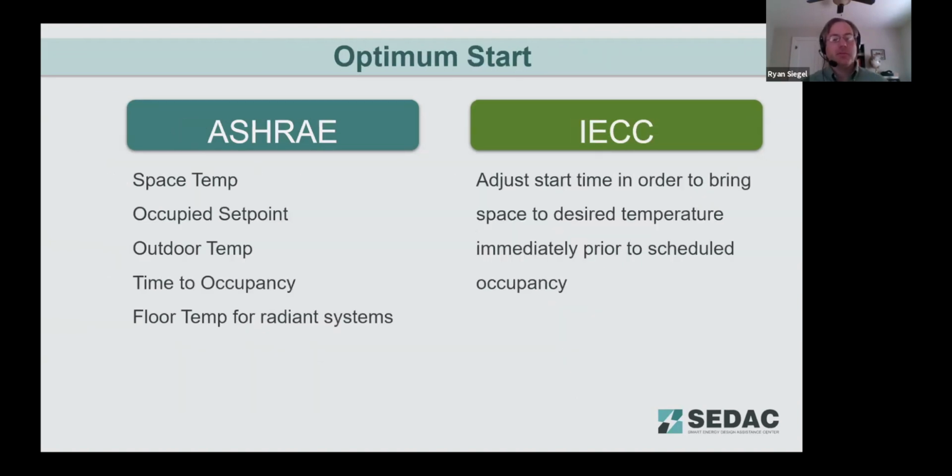As far as optimum start, ASHRAE calls out they're much more specific as far as the parameters used for the optimum start. IECC just states that you need to have optimum start time. And something I will note here is both of these are very temperature focused, and understanding that humidity does have an impact on comfort, and as we've touched on a few different times here today, as far as humidity and the potential for mold if we're not properly controlling for that. Frequently that may be a symptom of a larger issue of oversized equipment where we haven't been able to drive that moisture out of the air far enough away from that 60% limit that we really want to stay under.